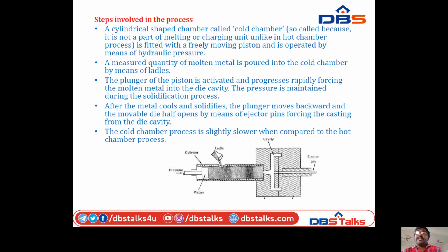A measured quantity of molten metal is poured into the cold chamber by means of ladles. The plunger of the piston is activated and progresses rapidly, forcing the molten metal into the die cavity. The pressure is maintained during the solidification process.